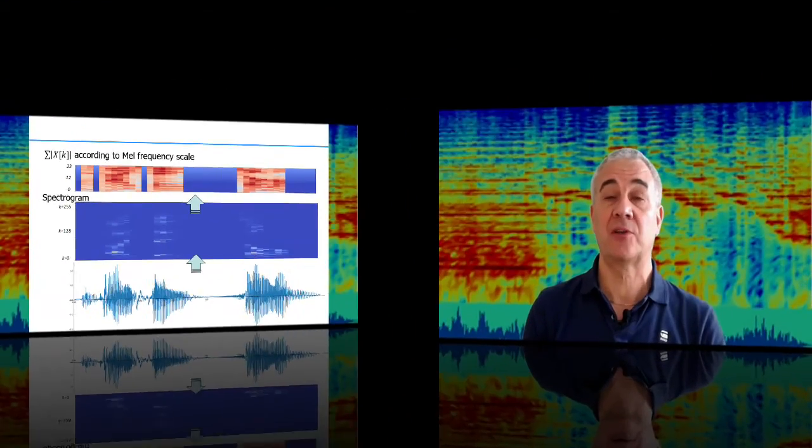From this you see that convolution using the DFT is fairly straightforward, of course not forgetting the circular extension. But also that the use of the DFT for signal analysis is often only a first step, after which many more analysis and possibly machine learning steps will follow before the final result is obtained. And that is how computer scientists see signal processing and the DFT. It is a great means for efficient FIR filter implementation, and it also provides us a means for characterizing a signal in terms of its frequency content to be used for recognizing, understanding and predicting the content of all sorts of signals.